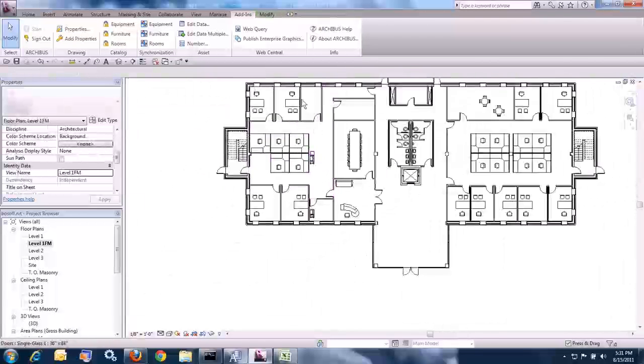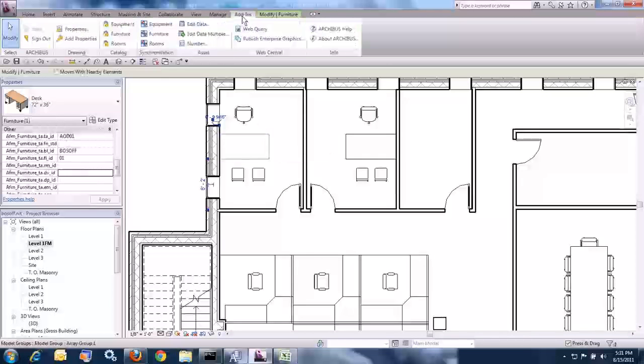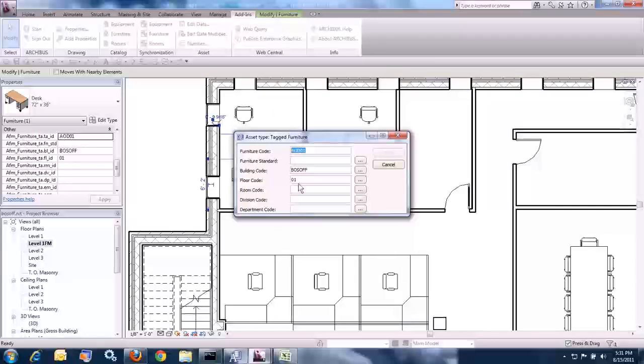What about pieces of furniture? So let's go up here, let's take our desk, our add-in. You'll notice that it's already numbered for us. Again, just to save time, I've already done some of this. So I have AOD01, I have AOD02. So let's edit data. Again, remember that these up here are assigned to specific rooms. So this is room 100, we'll save that.